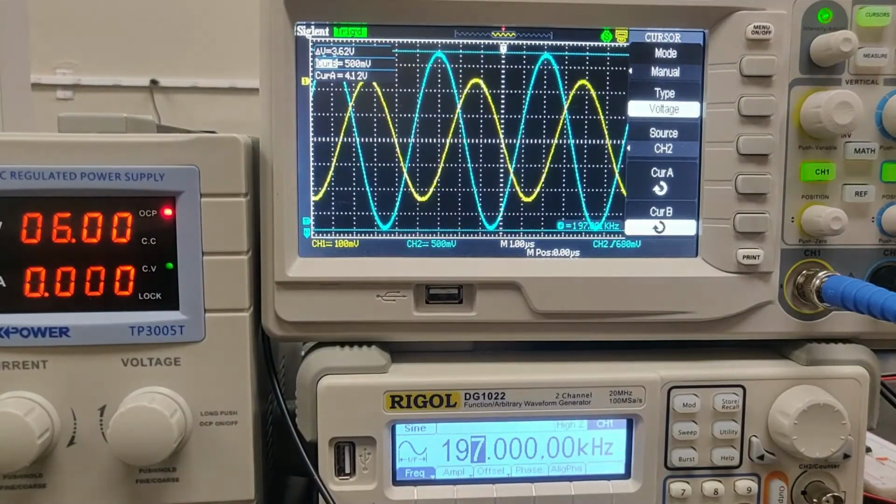So for this particular circuit, this inverting amplifier, our equation really is V out is equal to A times negative Vn, the negative V internal. So with that in mind, if we make that substitution into equation 2, with the understanding that A is a very large number and some things fall off to 0, you should be able to solve for it.